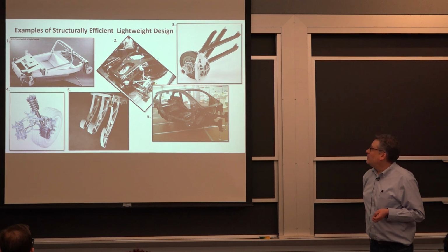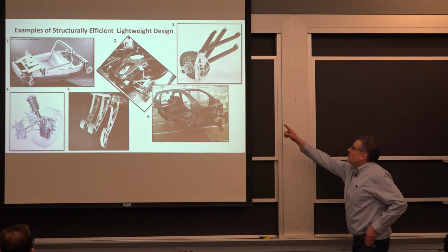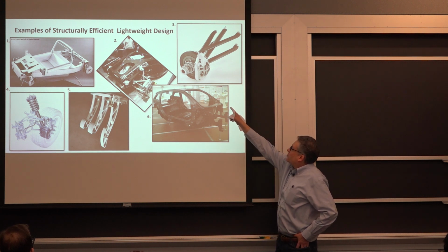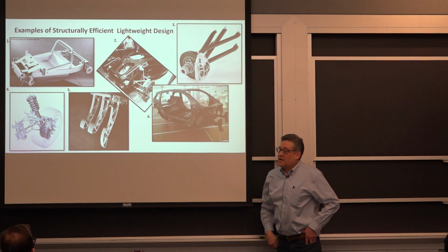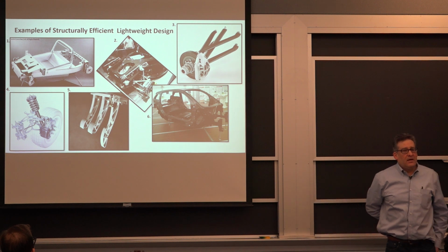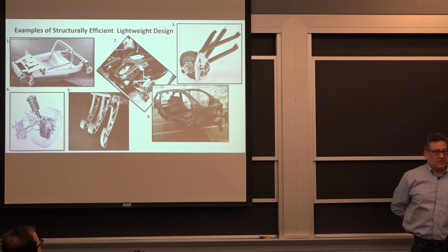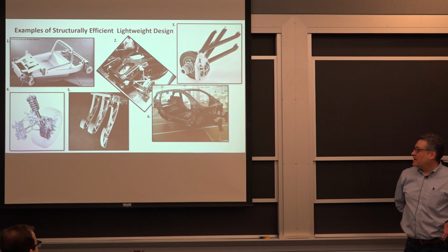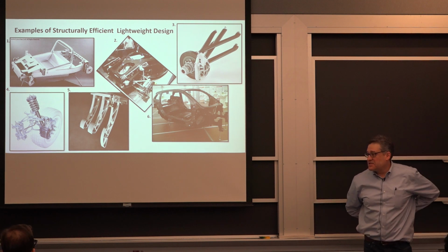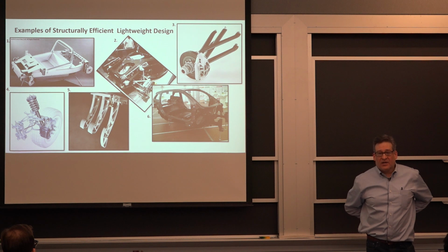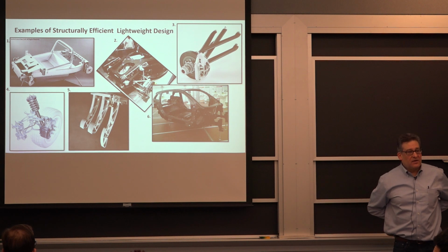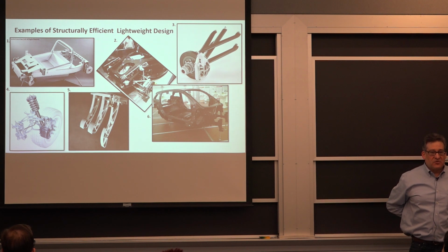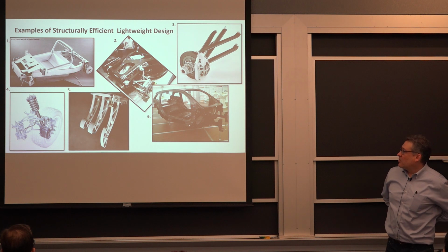Number 3 here, what I wanted to show was this brake rotor, which is carbon ceramic matrix composite, and then the caliper. The caliper was designed using this topology optimization tool I keep spouting off about, and that allows significant weight reduction. The number 4 there is the suspension system control arms off an Acura NSX from the 80s, and I think this is one of the earliest examples of an auto manufacturer using topology optimization to design the geometry of that control arm.